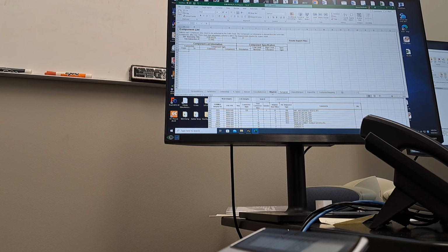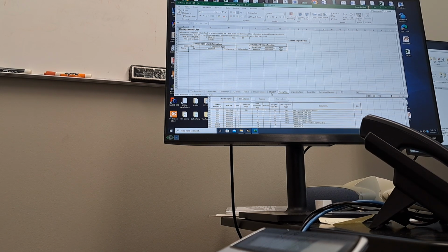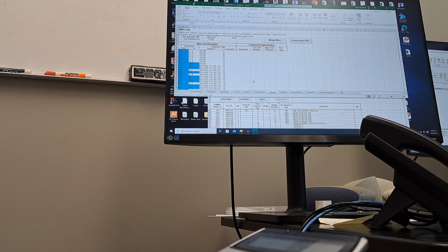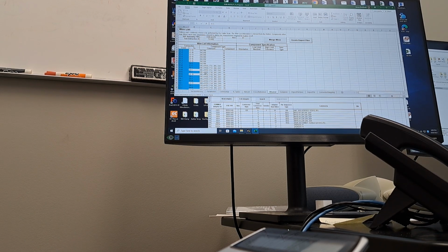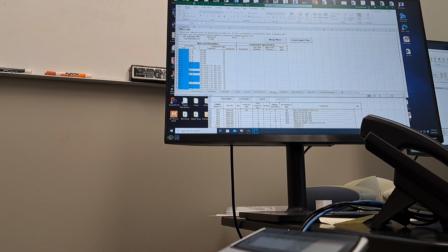And you guys have flexibility to use this tool the way that you want. But one of the standards that I do is I let the net list specify the things that show up in the wire list, and I don't put any components in there. Okay, and we'll go over why that is as we're going along. So you use the net list only for the net names? Yeah, well, and only, I mean, everything.